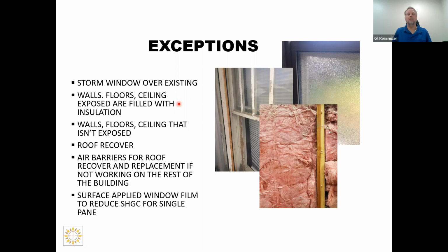Unless I'm building a brand new wall, it's really tough. Let's take it one step further. How many live in a climate zone where continuous exterior insulation is required, and I'm replacing 6 feet of exterior wall? Are you going to make them put exterior insulation on the outside? Give me a break. That's not what the code's for, I can tell you.